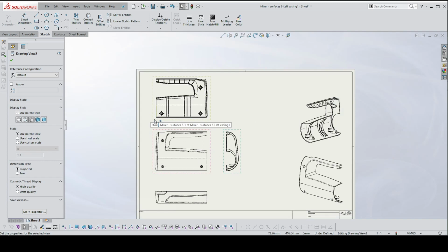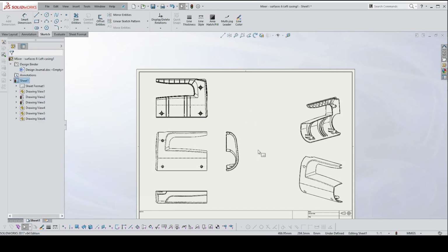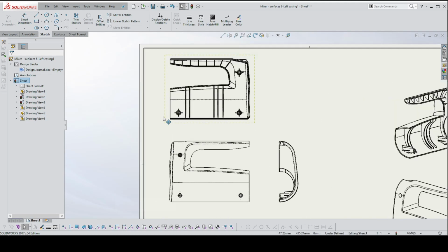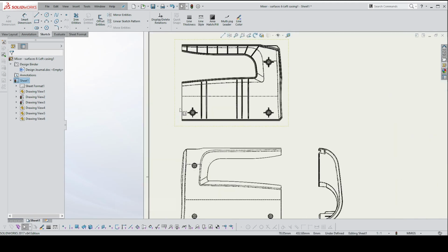So how do we dimension this? The steps that I want you to take is to put in your datums first and then proceed from there. So what is a datum, you may ask? My second years already know what it is. For those who've not heard what a datum is, it's a starting plane, right? It's not a starting point or even a starting line. You've got to think of it as equivalent to a plane, but it's going to appear as a starting line. So it's essentially going to be some plane that you select from which to continually dimension mostly the positions of other items. So let me show you one to start with.